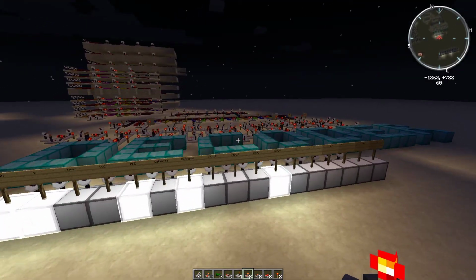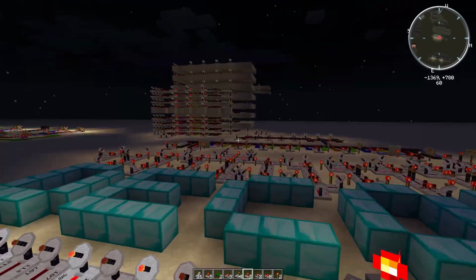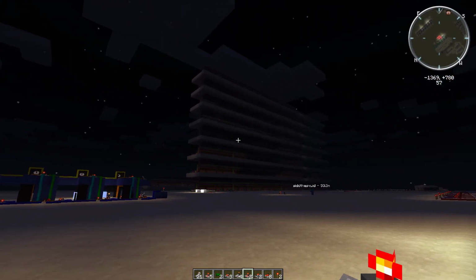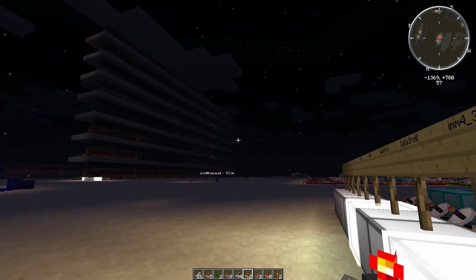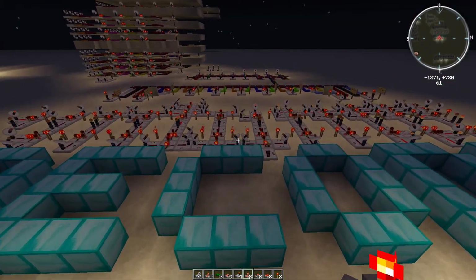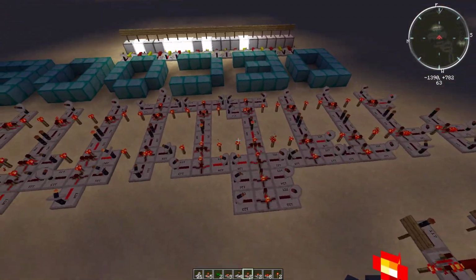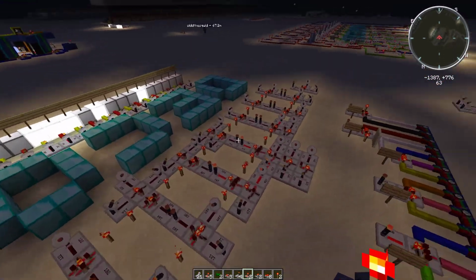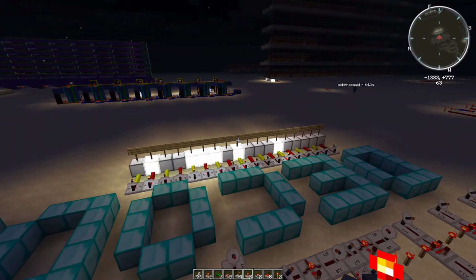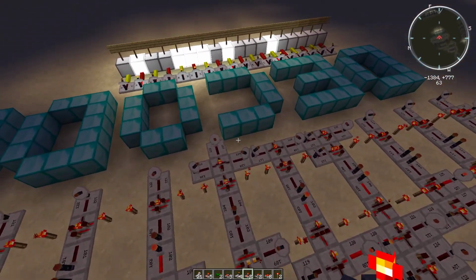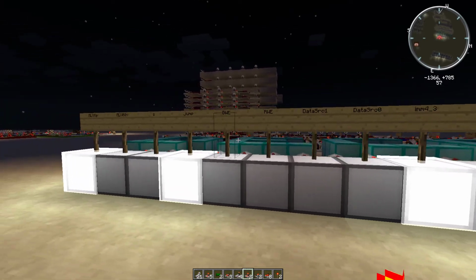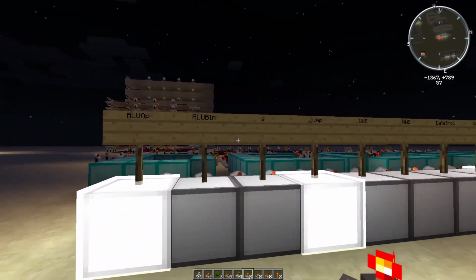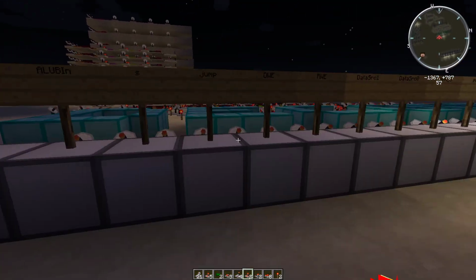The instruction decoder is essentially looking at the bits. In the back we had a bunch of toggleable switches, and these switches were basically giving the name of the instruction in binary. And here we have the equivalent of a massive lookup table, which takes those bits in from the instruction memory and is able to decode the instruction. These control flags right here, our opcodes, are lit up according to what is on per instruction.